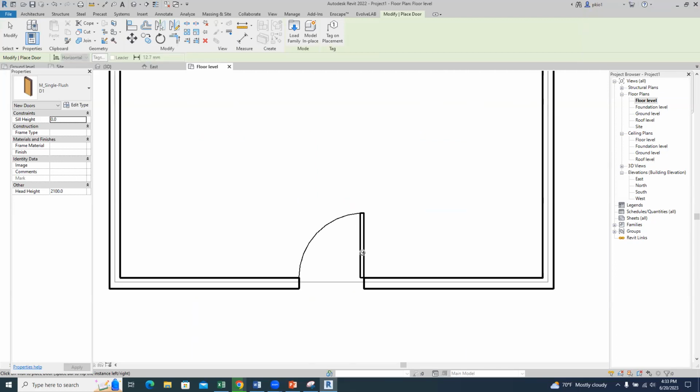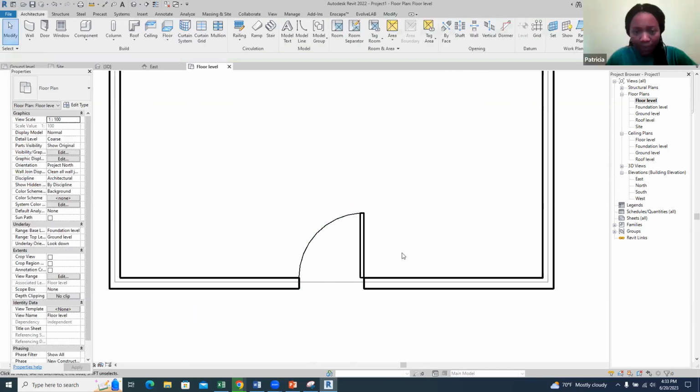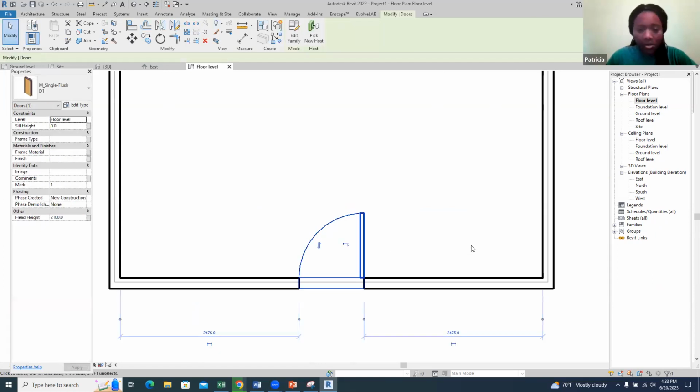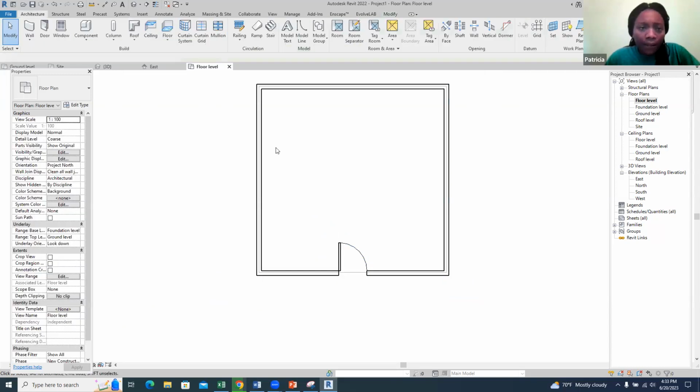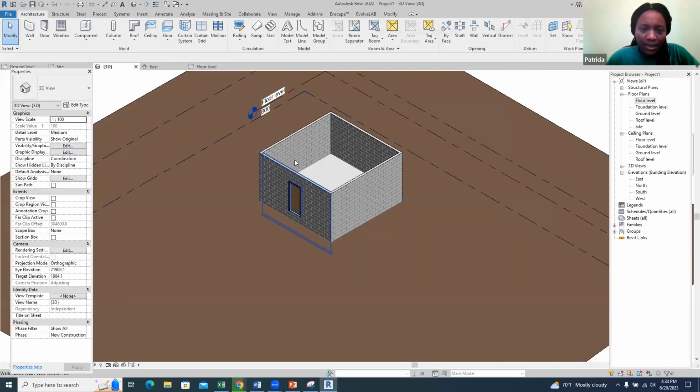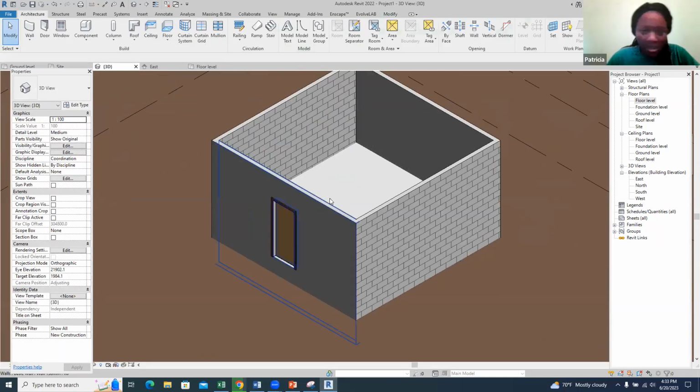And then even with this door in place, I select the door first, and then I hit my tab button. It will rotate the door to all the sides. Which one do you prefer? Or you can click on the arrows and then get it to which swing and which side you want it to go to. And most times, anytime you do something, you want to see it, does it look okay? Do I want to change something?